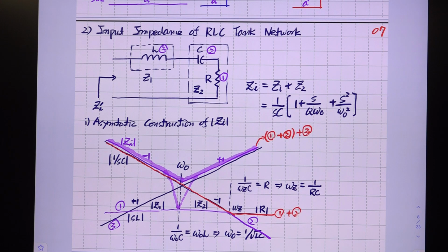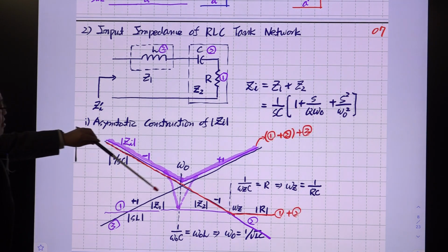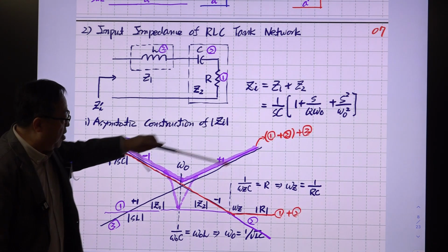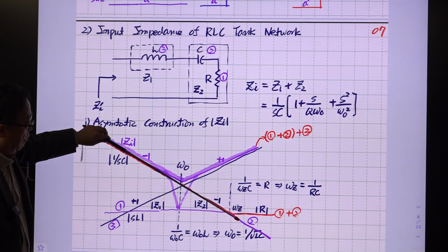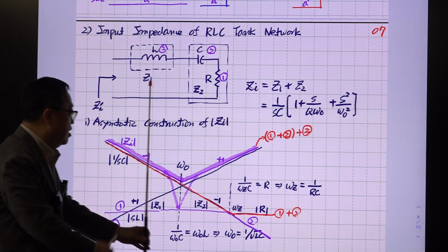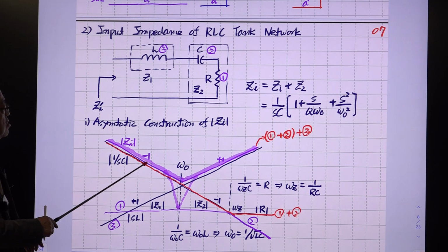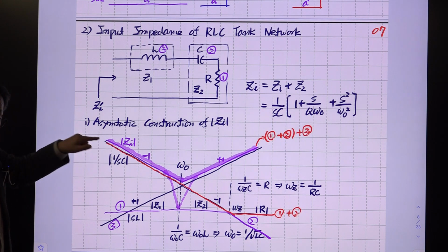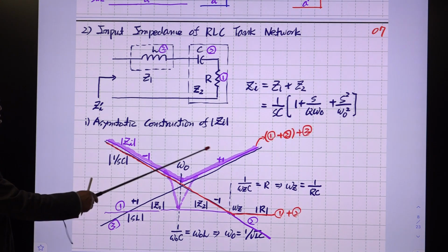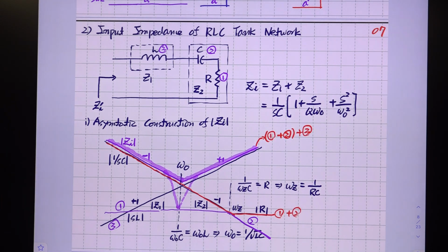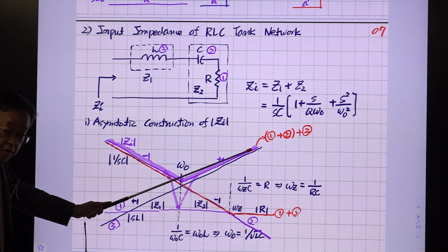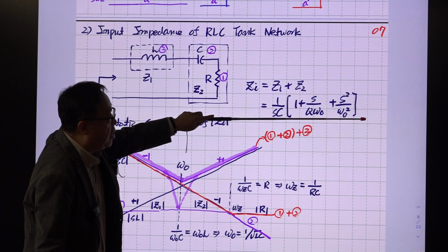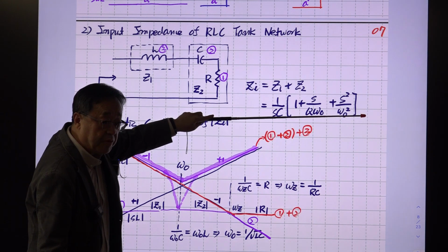Right? In terms of equation, this part has this slope, which is this 1 over SC, the equation of this capacitor part. All right? At this resonant frequency, the slope changes from -1 to +1. -1 is minus 20 dB per decade slope, and +1 is 20 dB per decade slope. So you have a slope change from -1 to +1. There is a double pole. The double pole is here. So we have the double pole equation. This is the standard form for the double pole equation.